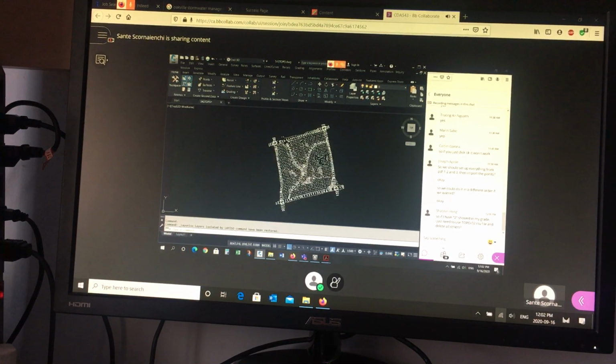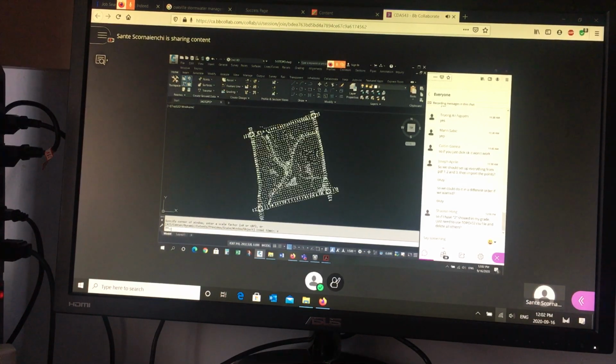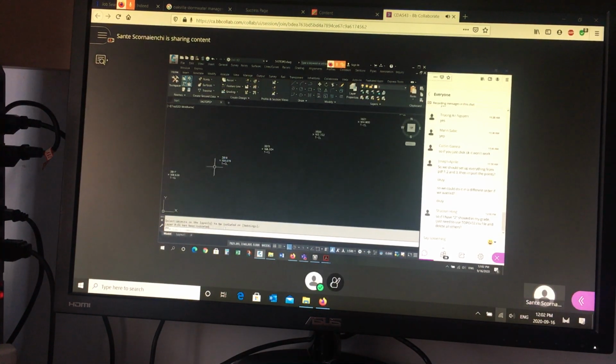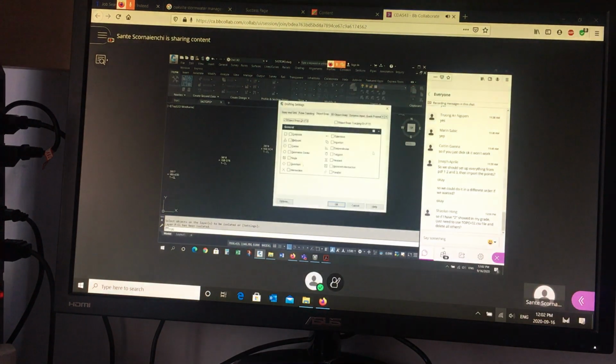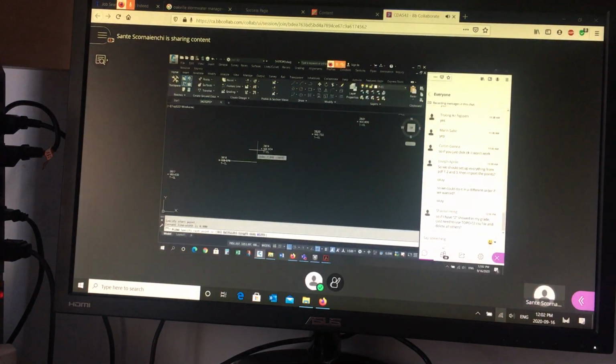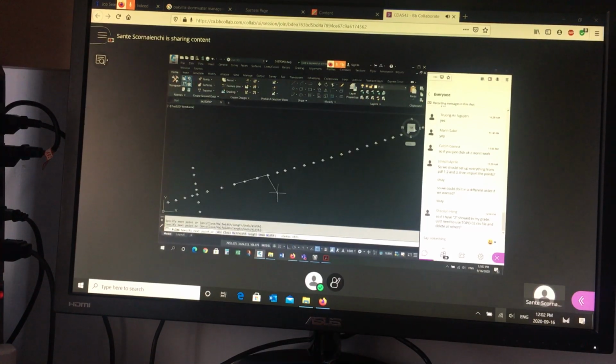I could do this if I want. Go to that center line layer. Create a new layer for the line. Change my O snaps to node, so I can click on all the points, and then draw a polyline from node to node to node to node. If you do that, you're fired. There's a better way. Node to node.